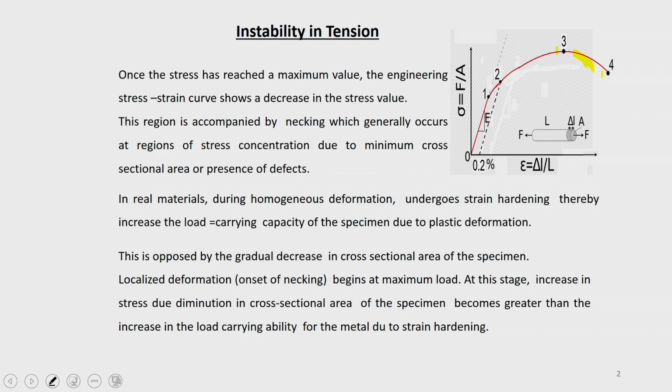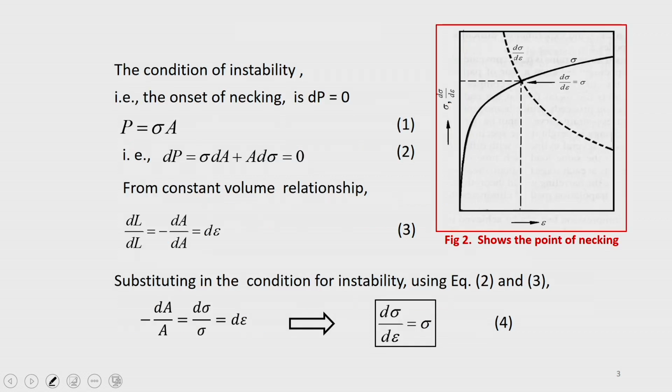4 here. So, during this time, though from this curve it appears that the stresses are decreasing, in the actual true stress-true strain curve it will be continuously increasing. So, these are the conditions we said. The strain hardening rate decreases, and the true stress-true strain curve increases, and at some point it reaches where these two are equal. So, the condition we get, this also we discussed.